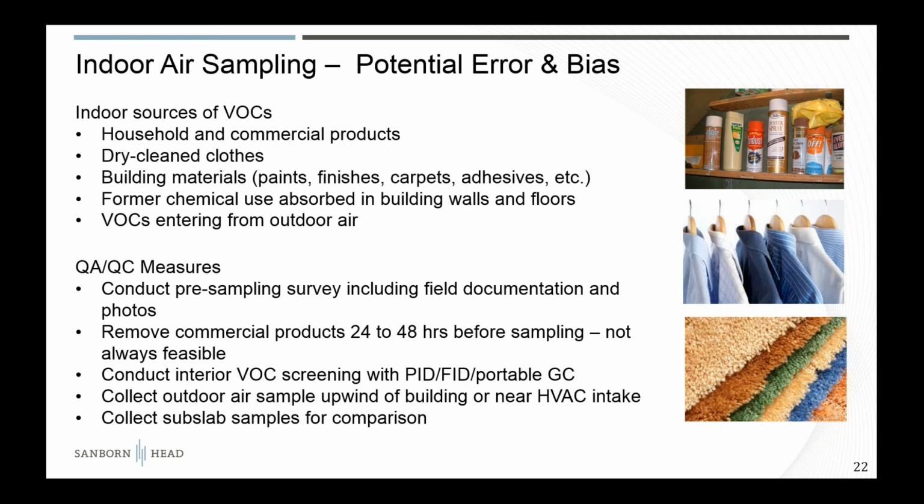The pre-sampling survey is a common recommendation in the various VI guidances, but this really needs to be done a number of days in advance if you're going to have a chance to get that material out of there and have the air turn over inside the structure sufficiently so that there isn't a residual. If you've got high levels of PCE in a residence and 24 hours later you do your sampling, there's still a pretty good chance there's going to be residual PCE after you remove the source.